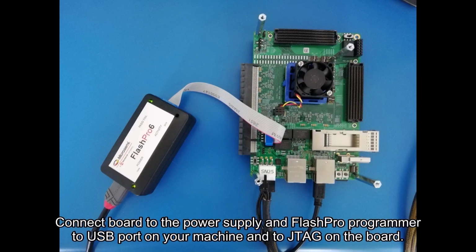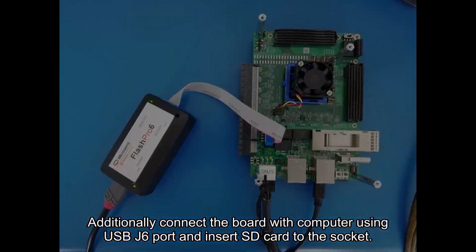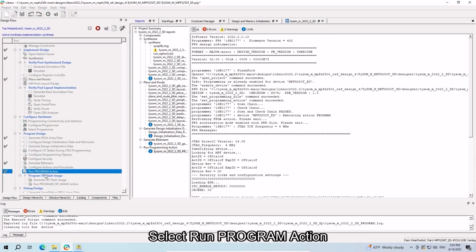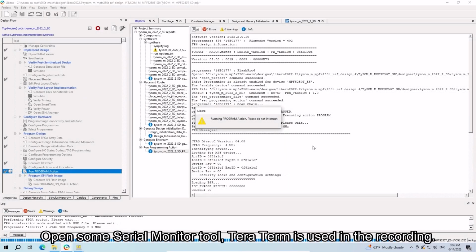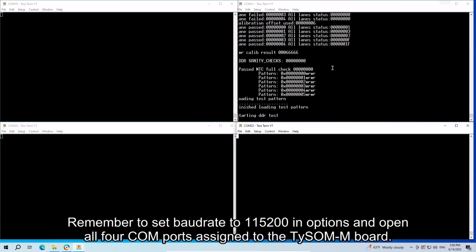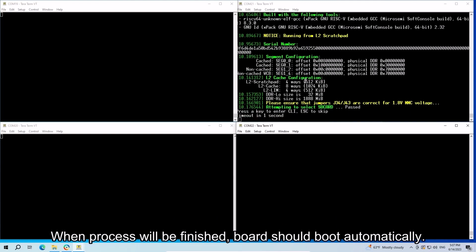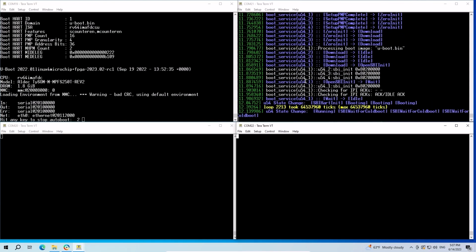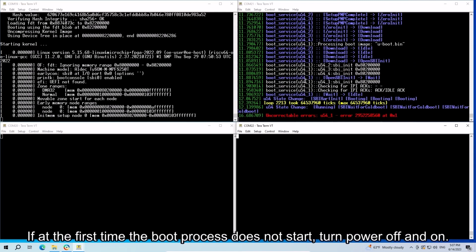Power the board and connect the FlashPro using USB for the machine and JTAG for the board. Use the USB J6 port for board-to-computer connection and insert the SD card. In Libero, select Run PROGRAM Action. Open up any serial monitor tool. In this recording, Tera Term is used. Set baud rate to 115200 and open all 4 COM ports assigned to the TySOM-M. The board should then boot automatically when finished. Turn power off, then back on if the boot process for the first time does not start.